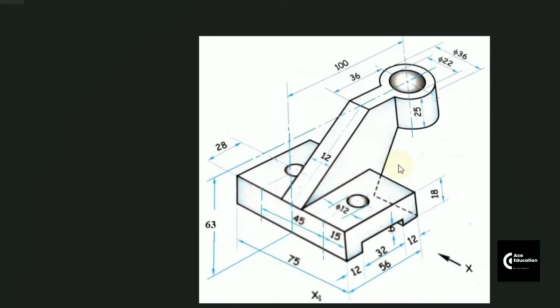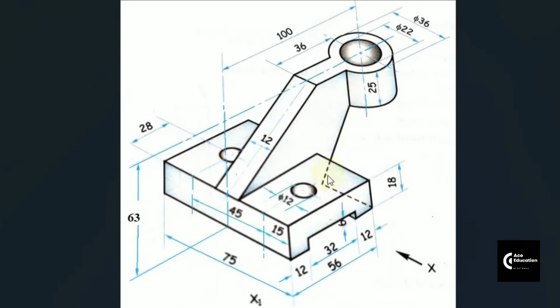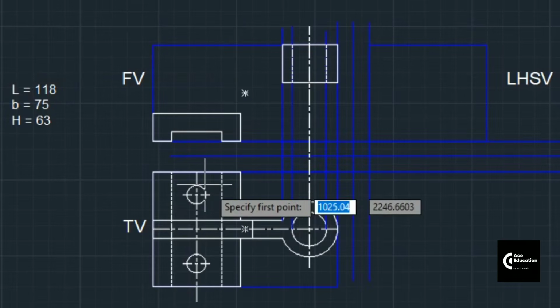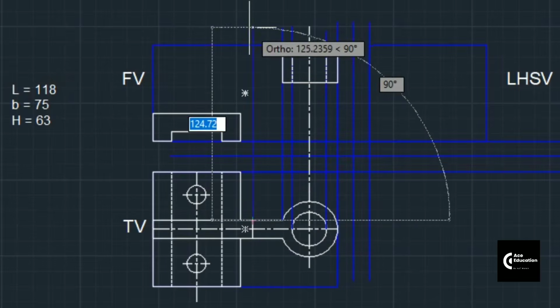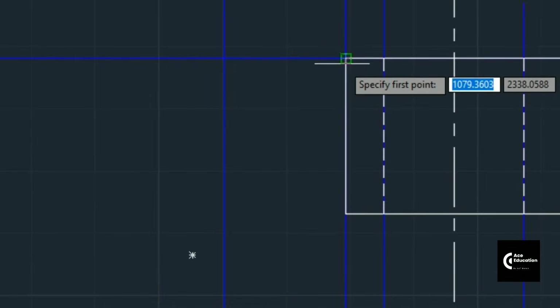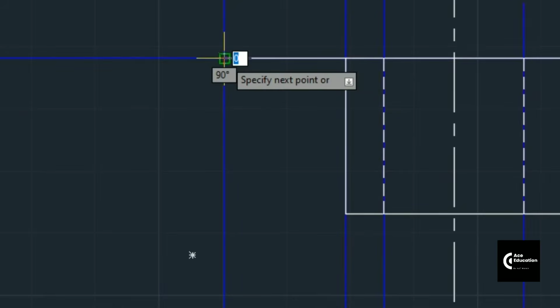So this is the cylinder you have just drawn over here. Now you want to create this vertical plate itself. You know that till this 36 mm position, it will be at the same position itself. So I'll take these positions vertically up so that I can draw a continuous line from this point to this point.